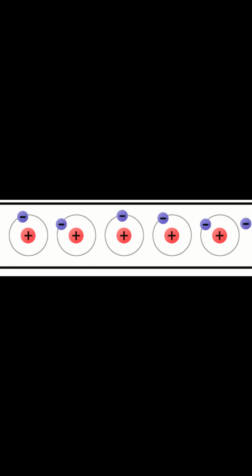Although both the neutral and grounding conductors are grounded at the power source, the grounding conductor is not considered to be a circuit conductor because current will flow through the grounding conductor only when a circuit fault develops.